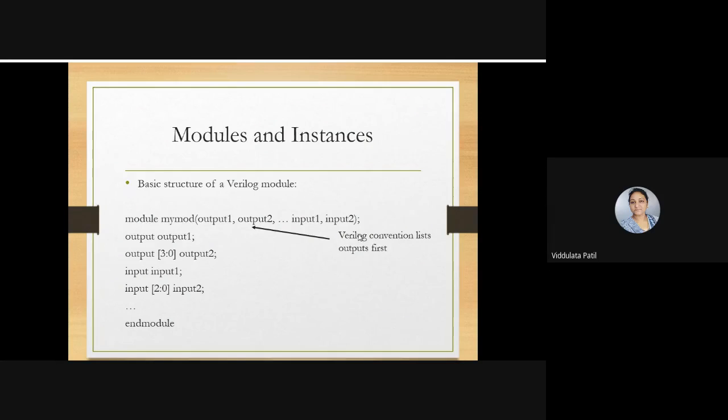Okay, so first use output ports, then declare. Here we are just giving the names, writing the names of these ports. After that we need to declare whether each is an input port, output port or inout. That declaration is done after declaring the name of the module, and after that there will be certain sequential or execution statements, and then the end of the module.